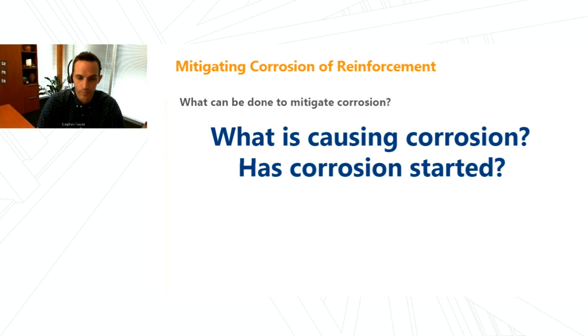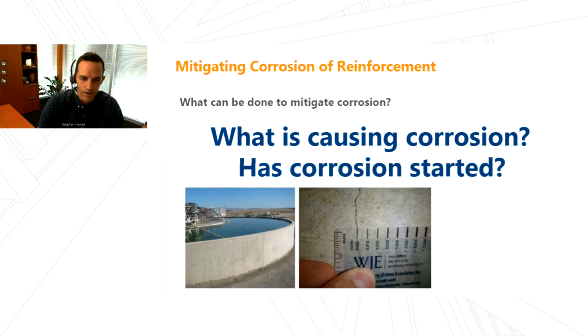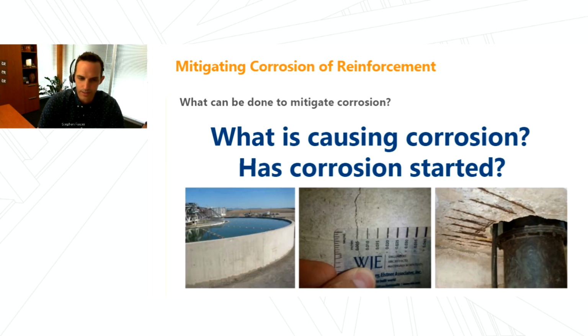And then coupled on top of that mechanism of what is, again, the when questions, right? Well, has corrosion started yet? Where are we at in this process of concrete that's new, that maybe does or doesn't have some amount of deleterious materials penetrating into that sponge-like material, or have we already started to see some surface damage, or certainly on the right where we now have corrosion exposed and we know the reinforcing steel is corroding, and not only corroding, but the concrete is spalled off, and now we need to do a different level of repair.